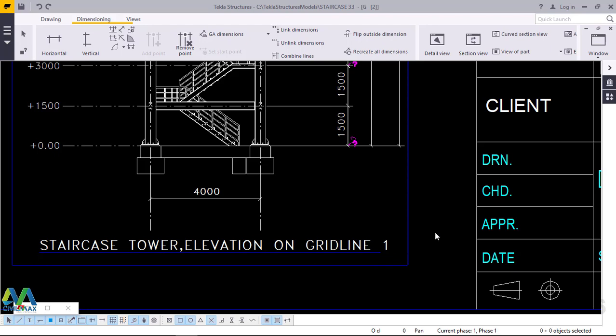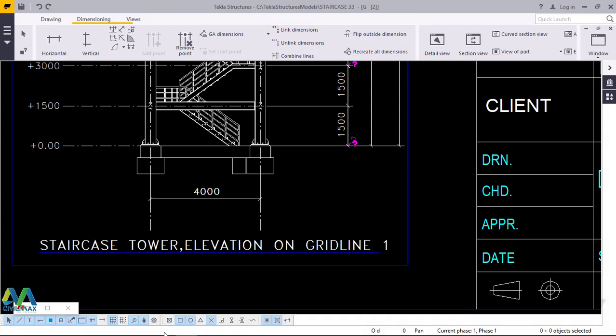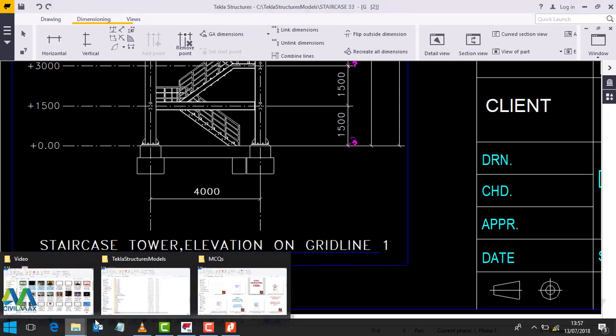Now, to convert this to PDF, we come to the same process, click print drawing, and pick your printer as PDF, and set your drawing to the center. And if you want to scale, you can fill in the scale in the slot, and you click print, and that will be printed. The printout will be sent to plot files, and this will be accessed. You can access the drawing inside your drawing folder, as I showed you previously.